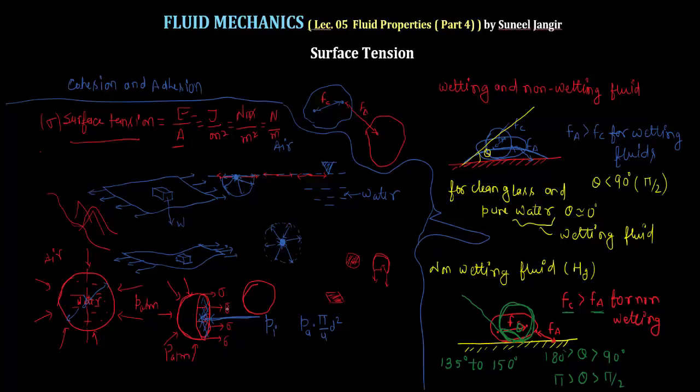Now the surface tension is also trying to compress the droplet. So this surface tension force is also acting in the same direction. Sigma is the surface tension, and it is acting over a line, that is the periphery of the circle, so that is pi d. The resisting force against these forces is the internal pressure acting over this area, so that is P I into pi by 4 d square.